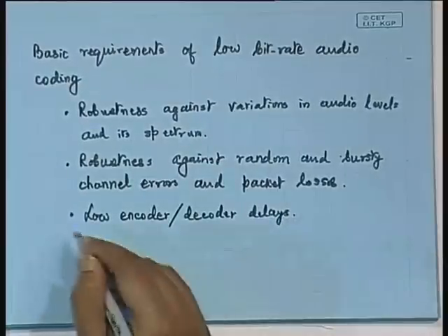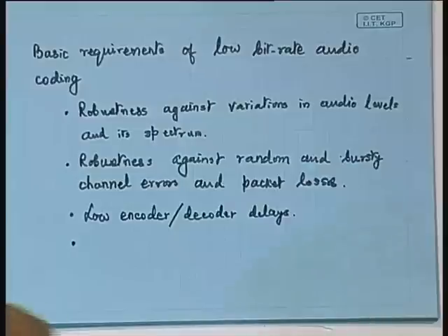Okay. And I was mentioning about the kind of burst errors that can happen, or in general I should say channel errors. Okay. And the channel errors, not only should we talk about the robustness, but also the effect of channel errors should not be catastrophic. Under ideal situation it is the best form of encoder, and in presence of channel errors it is just losing its track.